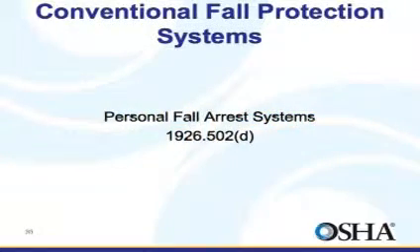Lastly, we'll take a look at what may be the most widely used form of fall protection used in residential construction: personal fall arrest systems. A personal fall arrest system must be designed so an employee cannot free fall more than 6 feet or contact any lower levels, bring an employee to a complete stop in 3.5 feet, and have sufficient strength to withstand twice the potential impact energy of an employee free falling a distance of 6 feet or less.